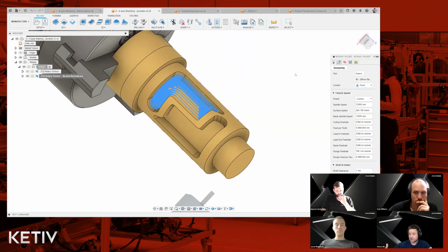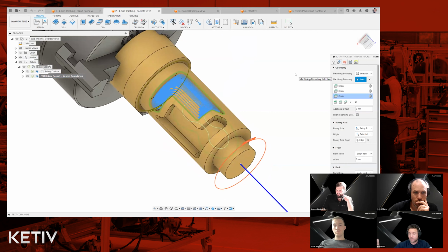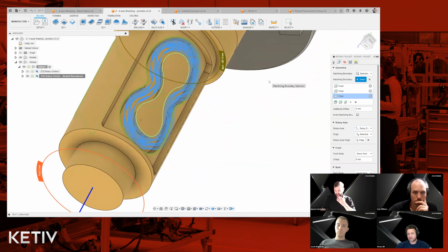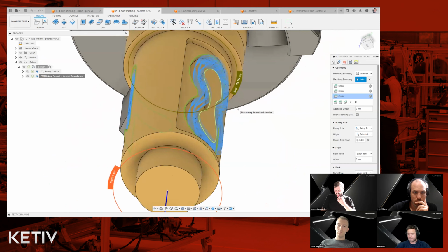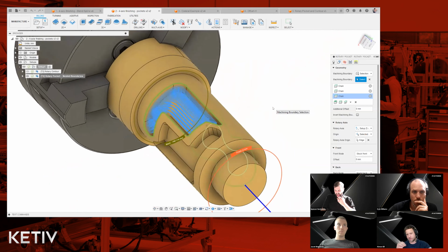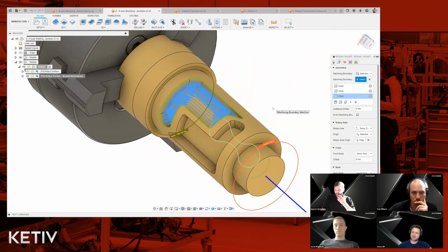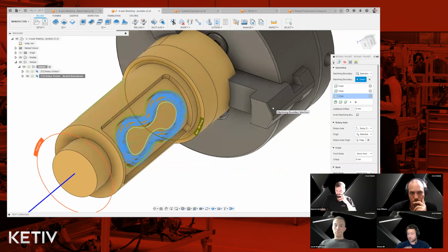Now, you can, as I say, use no boundaries, in which case it'll pick them all up. But you can also be more explicit and define certain boundaries. In this case, I've got a defined boundary on the one side, and then a pair of nested boundaries or nested curves on the opposite side. Now, the bit that makes this toolpath different to other strategies is that typically with other Fusion strategies, we use a cookie cutter style approach when we've got boundaries, in which case, if you did have a set of toolpaths on the opposite side that you had a boundary on, you could often have the situation where you'd have toolpaths missing because that cookie cutter basically extrudes top and bottom and right the way through.